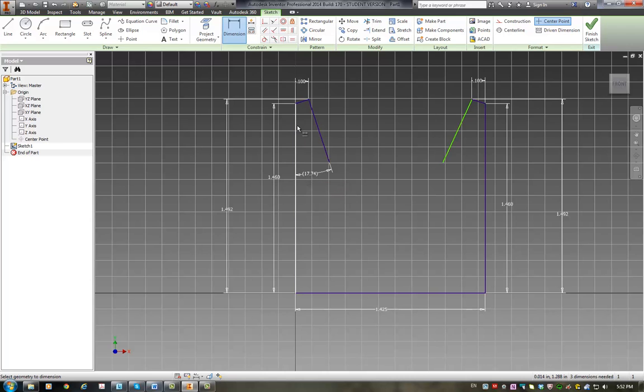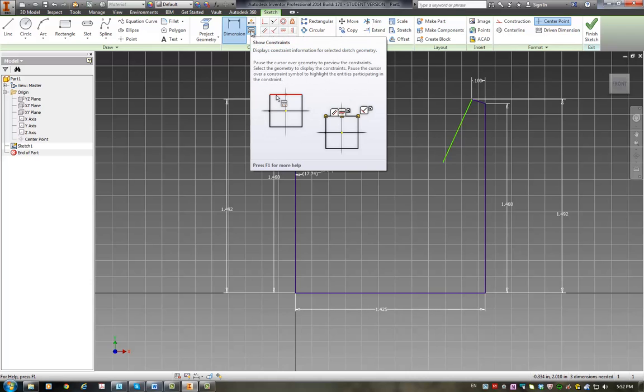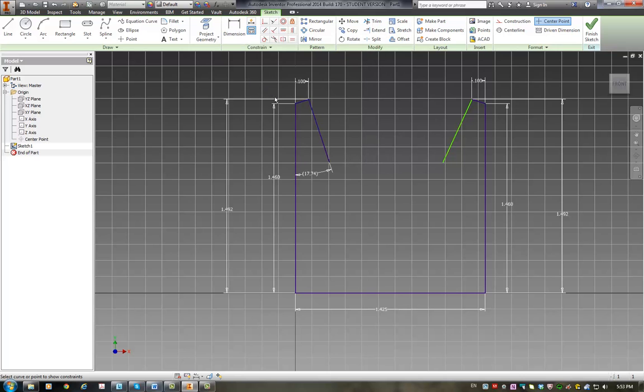And if you have an issue like this, it means that maybe the angle in between these two lines is 90. And in order to check that, I will have to turn on constraints. So I will select here show constraints, and I will select all the lines that I have. And that's exactly what happened. You see I have this perpendicular constraint here. Either you can delete this line and create another one, which is obviously not perpendicular to this one, or you can just click here on this X mark and then delete this constraint. And then you can try to create this angle again.